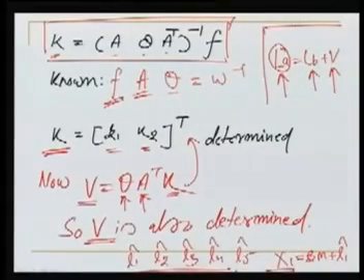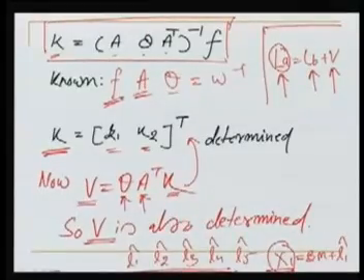Whichever route I take in that level network, I will get the same value of x1, and this x1 is my parameter, the unknown, the desired quantity which we wanted to determine by these observations. So this is the procedure of adjustment by condition equation method.